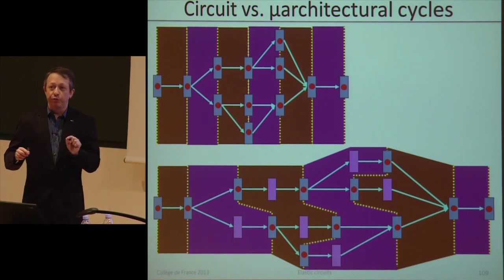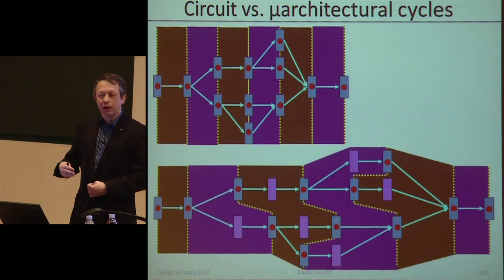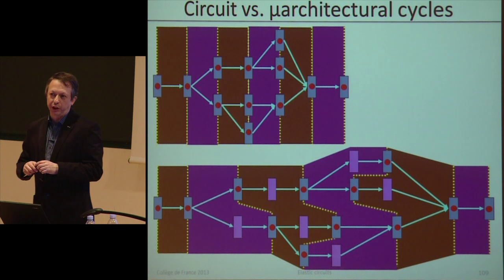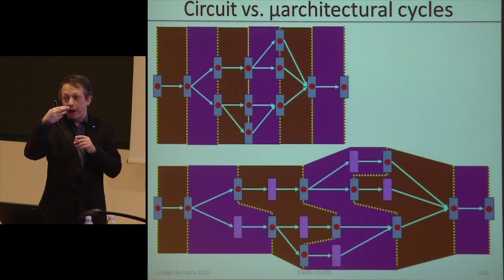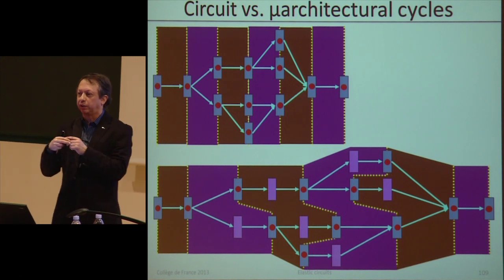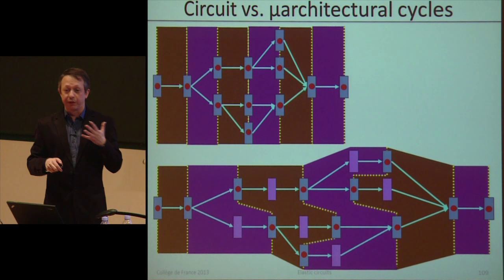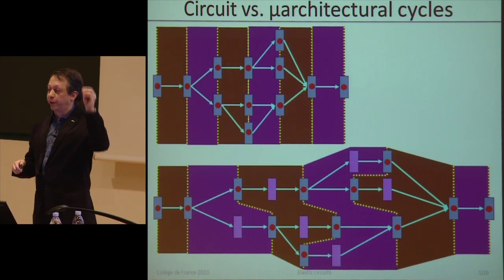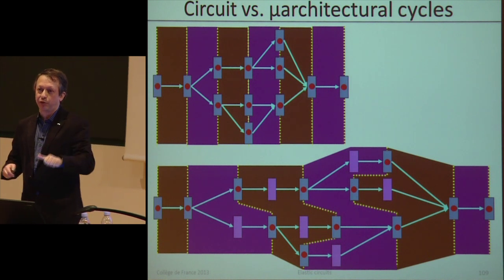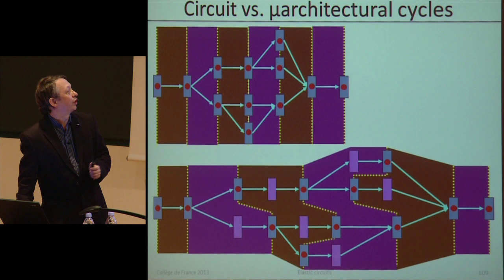It's like saying, okay, in a microprocessor, we can have instructions that are executed one every cycle. But maybe inside that cycle, we have microprogramming with microcycles. Okay? So the observable cycles are the same. And which are the observable cycles? The observable cycles are the ones in which the valid signal is 1. When the valid signal is 0, then it's not a valid cycle.